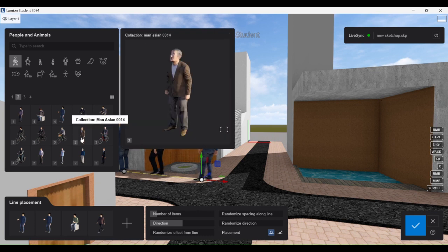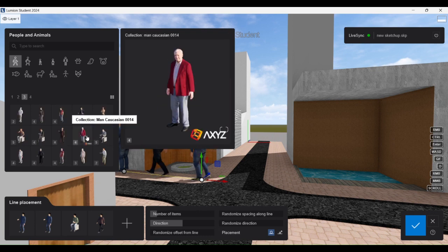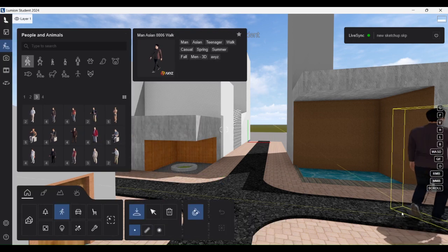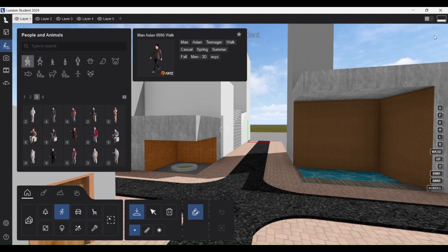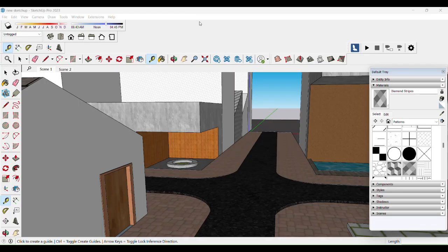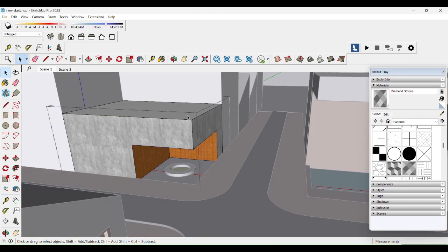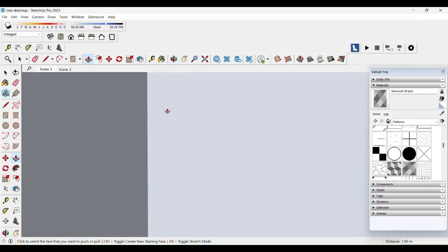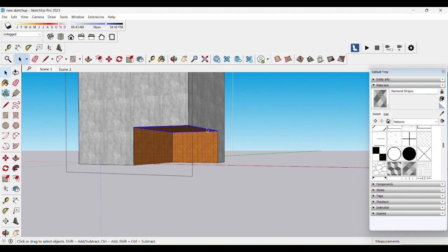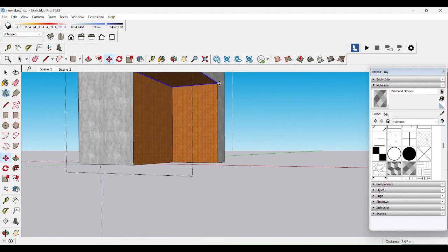Select everything, but the scale looks a little off from our 3D modeling to our Lumion elements. So that corner block is very small, and we want to edit that. Closing the whole file, doing the changes again and importing back is tedious. So you cancel this, switch off the live sync if you want. When you want to edit that, go back to SketchUp and select.